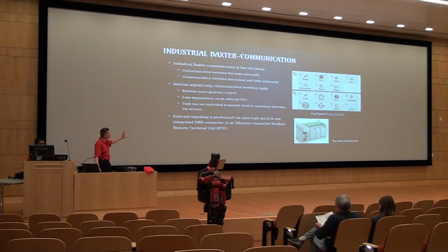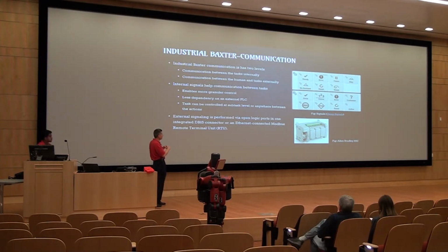So last summer, very quickly, the communication side of the picture. How do we communicate with these robots? With the industrial Ethernet standards, things have come a long way. So we're doing more and more with Ethernet, but there are a lot of legacy systems. RS-232 is still out there that we have to use. This particular unit will use Modbus. So we can use a variation of our Ethernet to do communications.